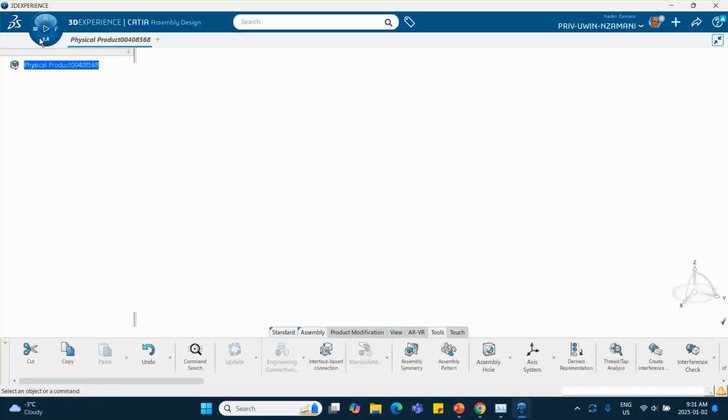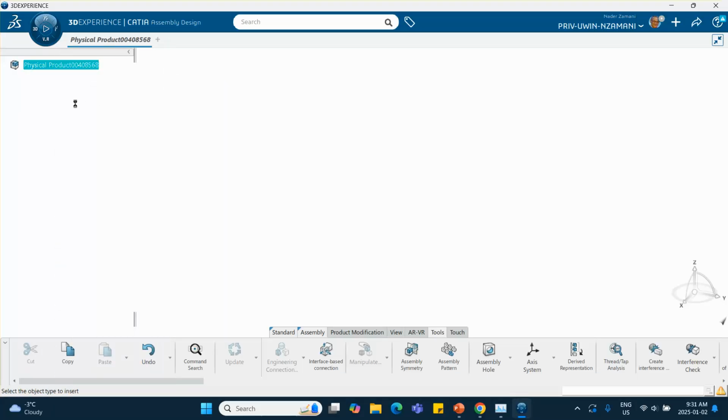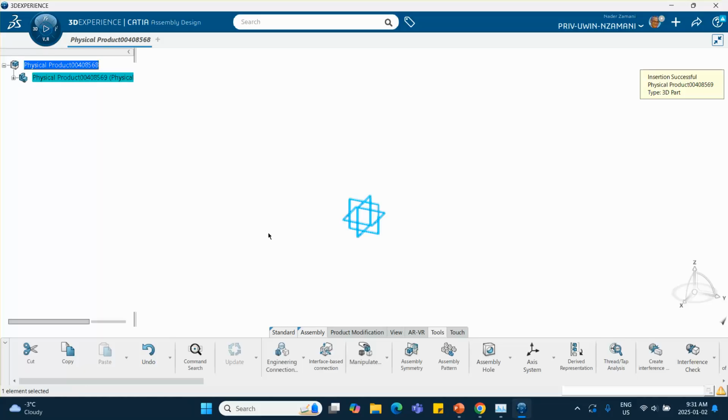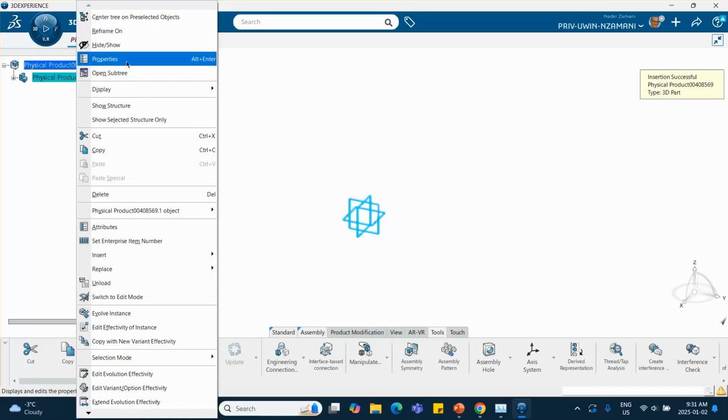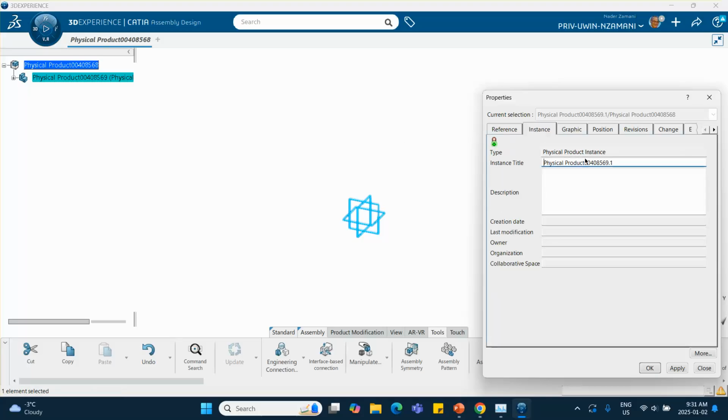Let me start with an assembly file and insert in it a 3D part. That's going to be my track. Just wait for it to pop up. Okay, so I'm going to call this thing the track. Right click, properties, track, which is incidentally stationary, obviously, and therefore the mass of it, although it has to be specified, is totally irrelevant.